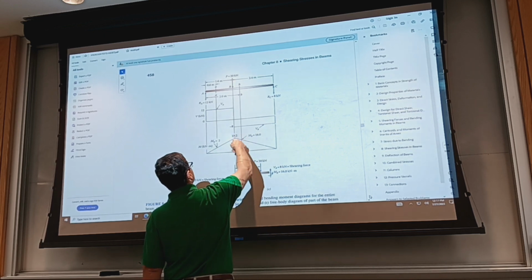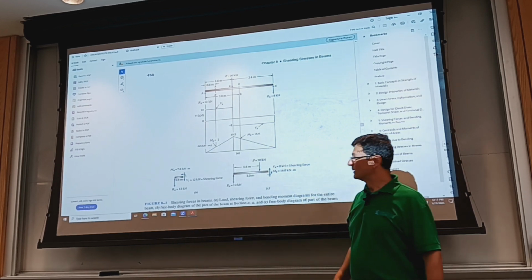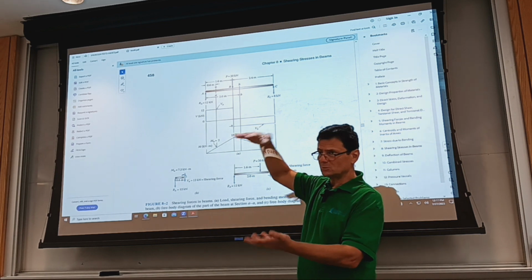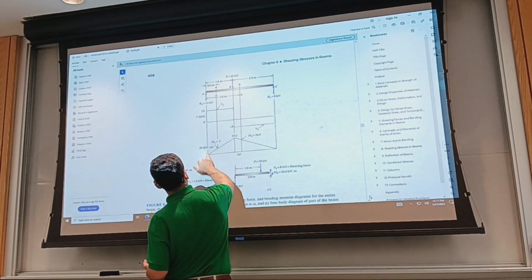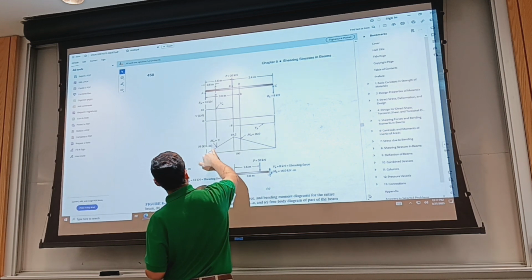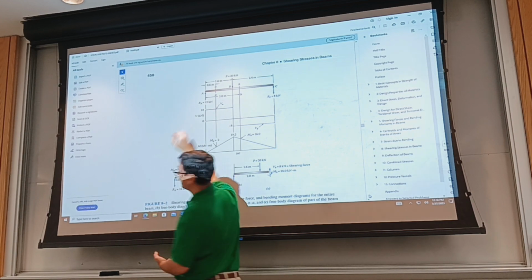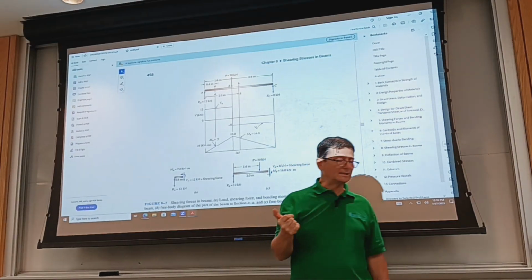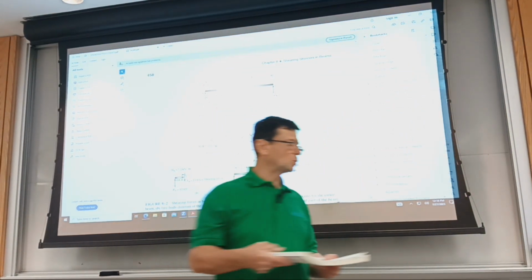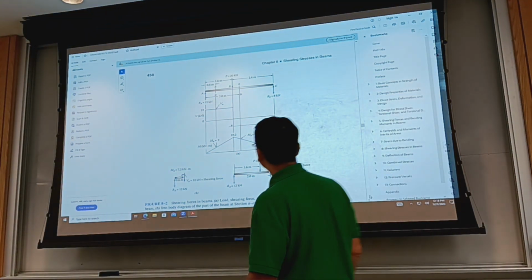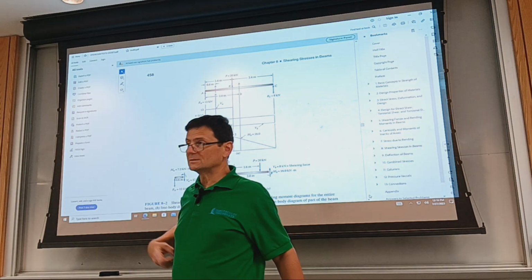So yeah, our concern is where the moment peaks, and we know that on the outer skins is where the maximum stresses occur. But if you're evaluating the beam close to the support, the net moment is less, but the shear force is large. So you can have failures occurring in a certain type of material like wood, or in short beams. The book has a list of cases where the shear force and the corresponding shear stress are significant.